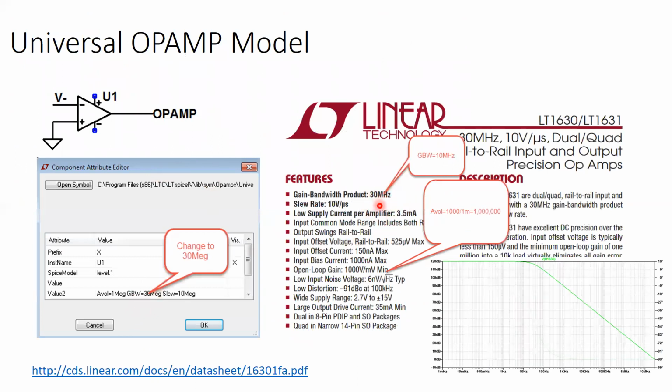That 30 megahertz isn't like a 1% resistor where it's very tight. It's all over the place. You might ask yourself, hey, I've got a low-pass filter right there. But you wouldn't use it as a low-pass filter because this cutoff frequency is bouncing around due to manufacturing tolerances. Really, the way this is used is, here's the frequency limitation. If I get too close to that green line, my circuit's going to stop working the way I want it to work.